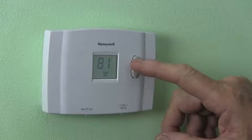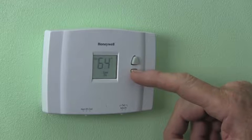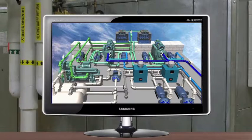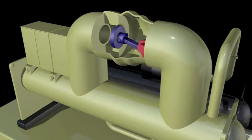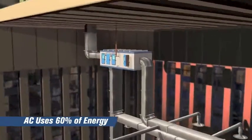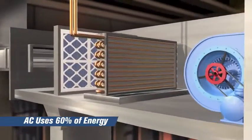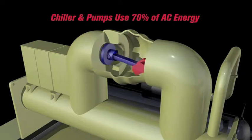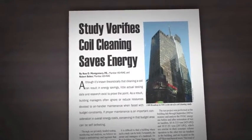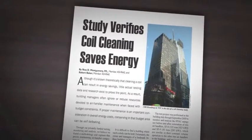To achieve the desired thermal comfort, either the occupants alter the thermostats or the maintenance department adjusts the chiller set point. In either case, this increases the electrical consumption of the chiller and pumps. In a typical office building, the AC system uses 60% of the building's energy, and of this, the chiller and pumps consume 70%. The 2006 ASHRAE published study estimated savings of 15 to 30% from a clean coil.